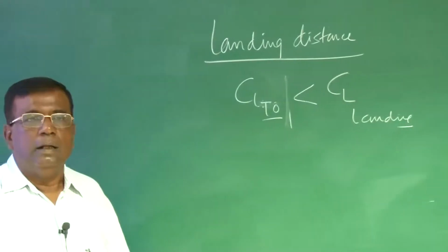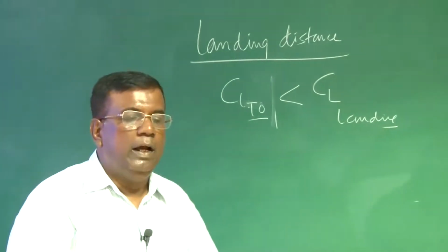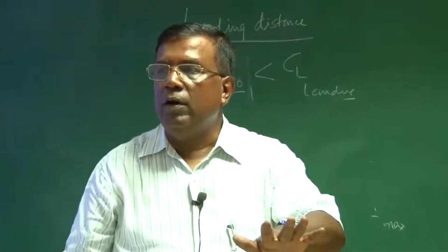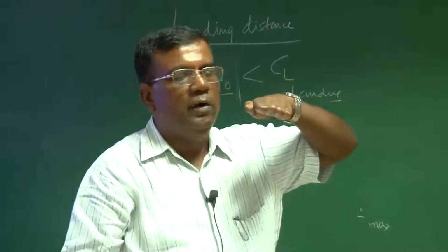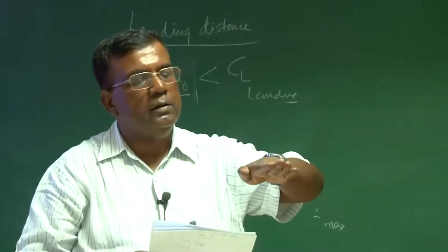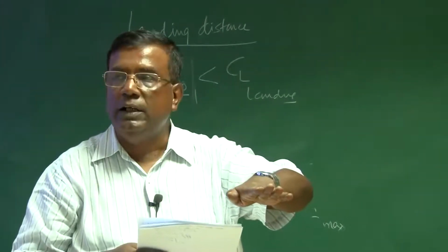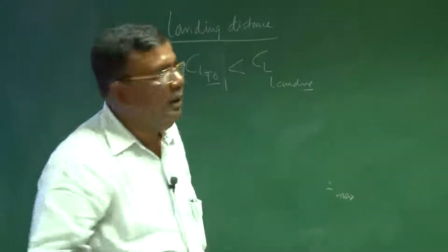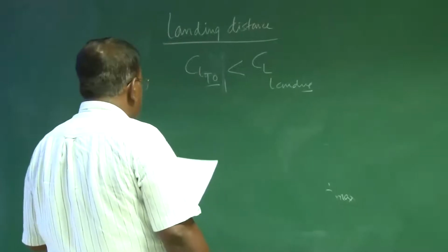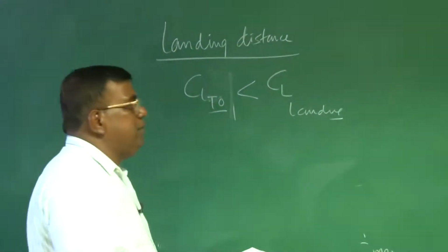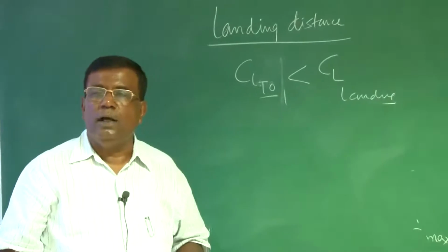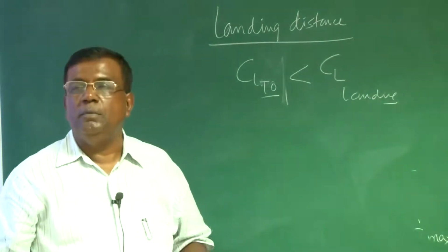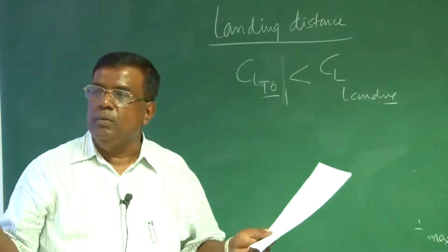Okay? And that is more so because while landing, you want your touchdown velocity to be as low as possible. You land like this, you come for an approach, then start coming down a glide slope of around 3 degrees, flare up, touch, go like this, okay, apply brakes. At a conceptual stage, whatever takeoff distance you get, you add 15% more or even 50% more and your landing distance will be safe.